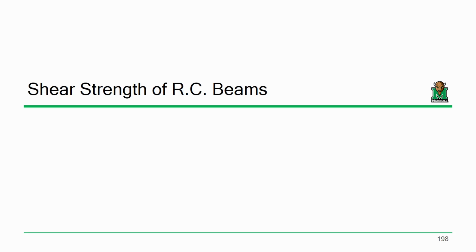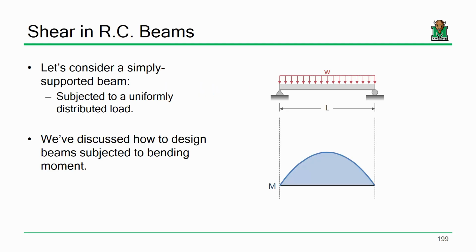But before we get into all that, I do want to take some time and actually review what's going on with shear and why it's important and all the mechanics associated, et cetera. So let's start off with this. If you left structural analysis unable to do this problem, I failed as a professor. A simply supported beam with a uniformly distributed load, I have got to believe you can do that, right? Moment diagram, WL squared over 8, all that jazz.